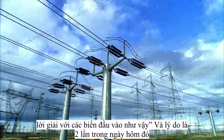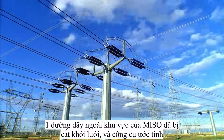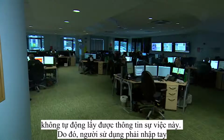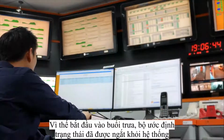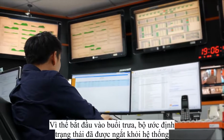And the reason it was saying this is that twice that day, a transmission line outside MISO's area had tripped offline, and the state estimator didn't have an automatic link to that information. Instead, it had to be entered manually, and it took a bunch of phone calls and troubleshooting to realize this in both cases. So, starting around noon, MISO's state estimator was effectively offline.